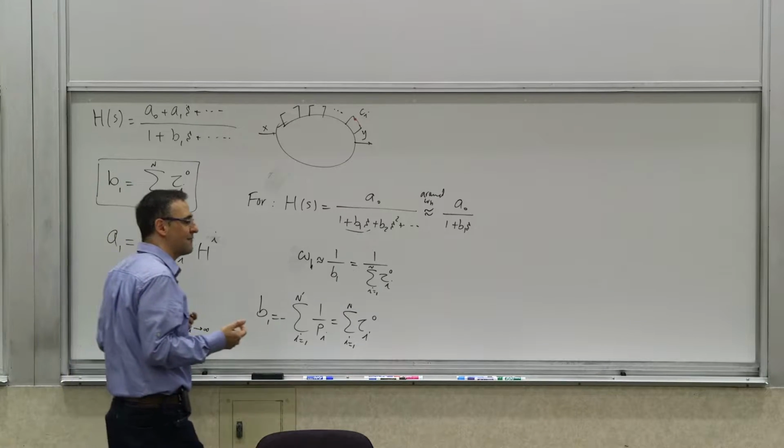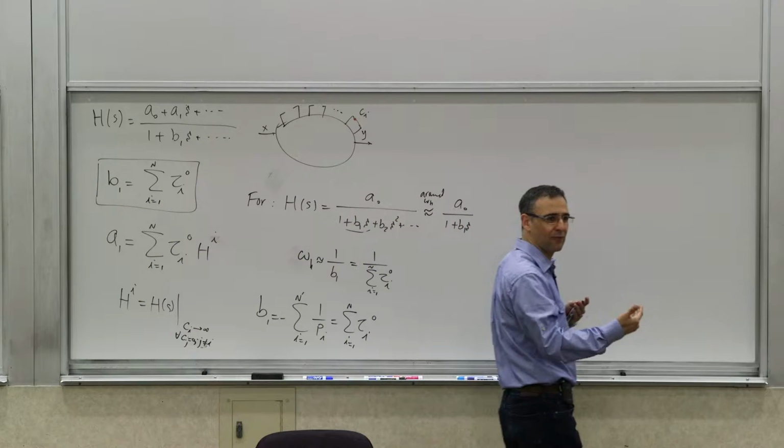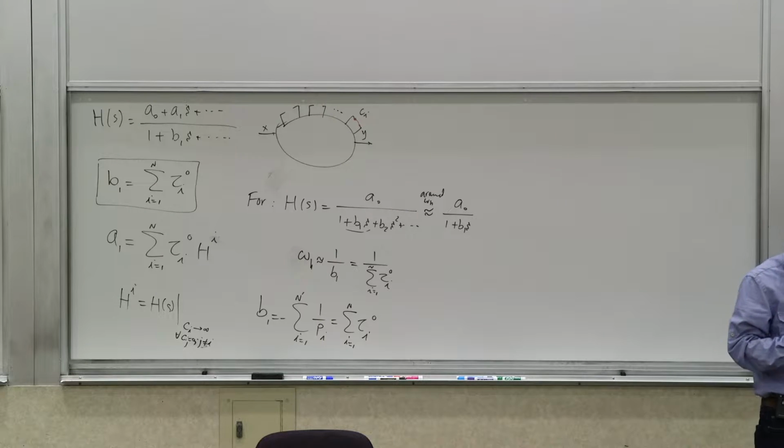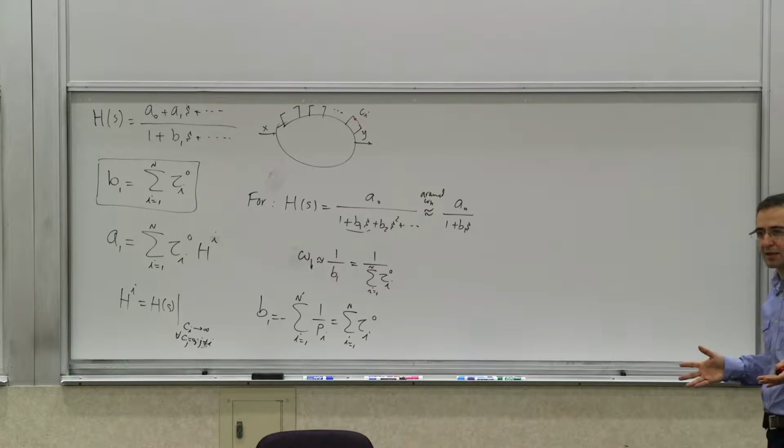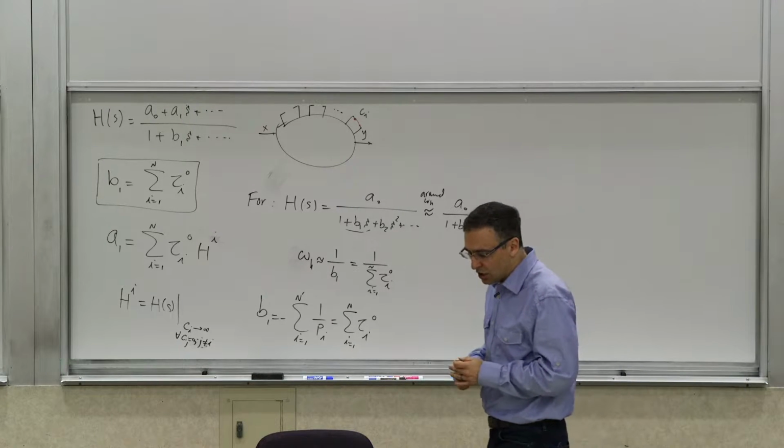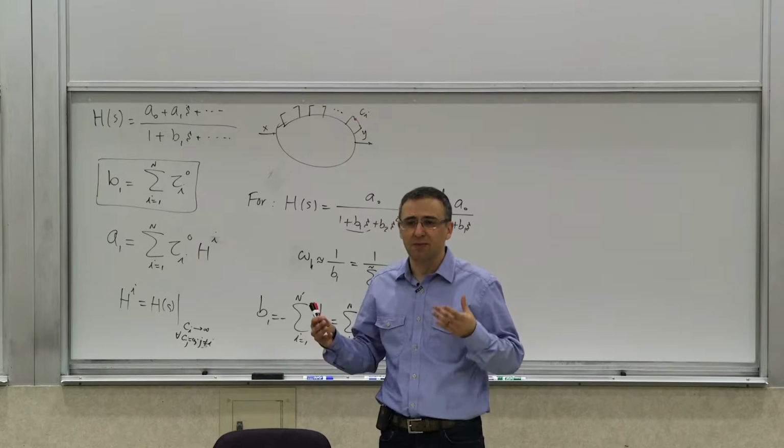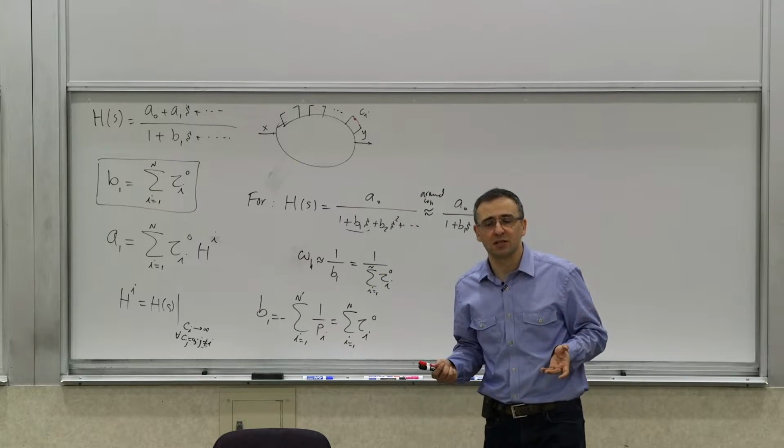And then when we added a buffer, a follower stage between the output and the load capacitance to make the resistance seen by that capacitance smaller, we saw that we significantly improved our bandwidth when we did that. And that's where we stopped. So that was a case where the estimates were kind of close, and we saw that it's always conservative.